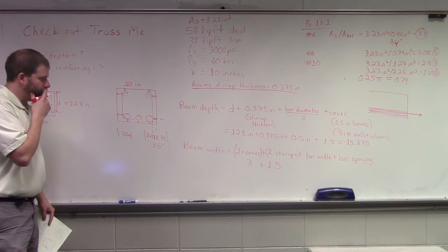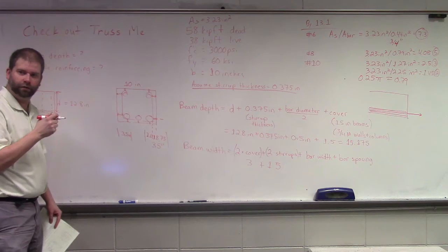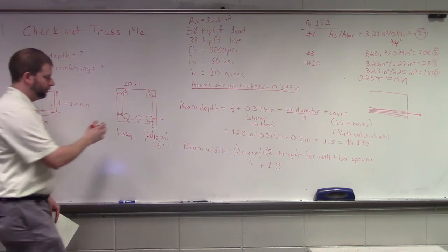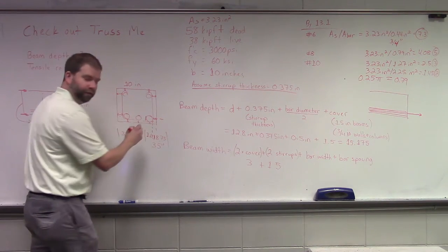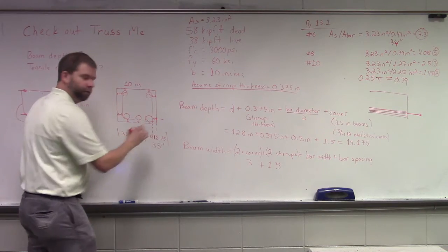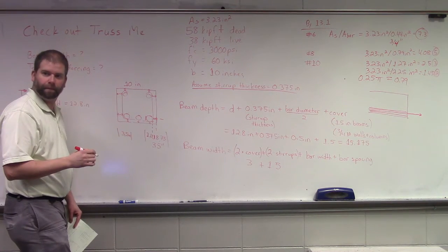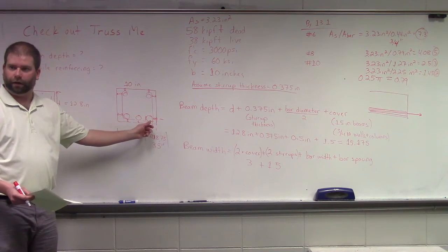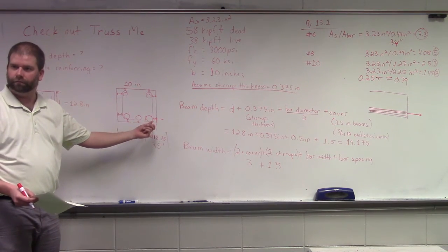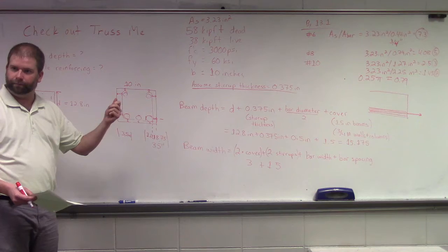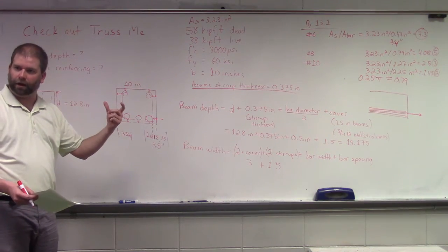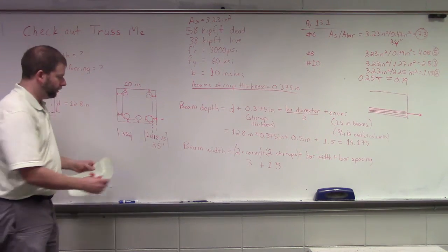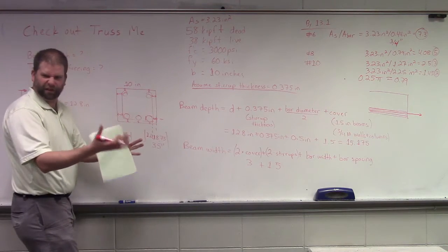So why do you have 3.5? I get you're using how big the bar is, but that's my distance to here, where the 1.5 needs to be? No, no, no. This is the thickness of the bar. I'm taking an inch and a half of cover, the thickness of our stirrup, and the diameter of the bar. That equals 3.5. So that gets us roughly 3.5 inches in.